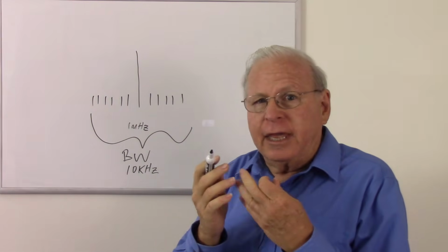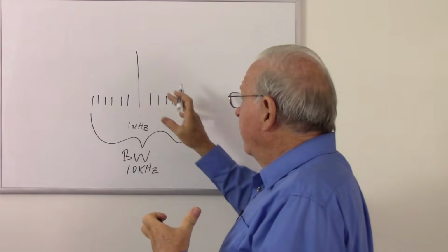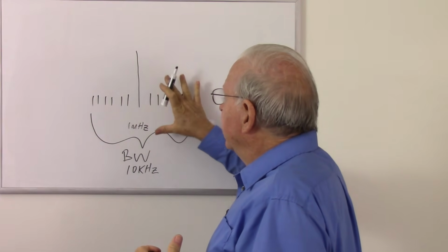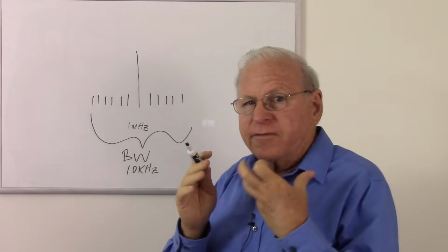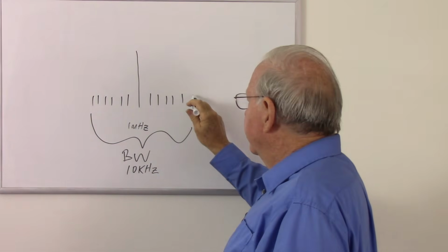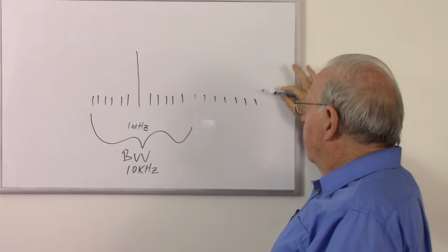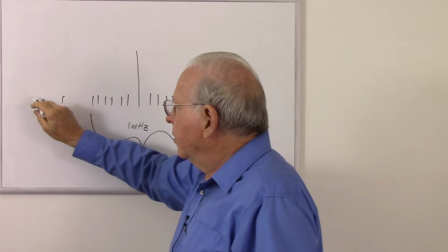And so if I'm talking, I'm producing frequencies up to 20 kilohertz. And so we're not going to get a very good approximation of my voice at AM radio. We're going to lose a lot of the higher frequencies because the 10 kilohertz bandwidth cannot carry those higher frequencies that go above the carrier and go below the carrier.